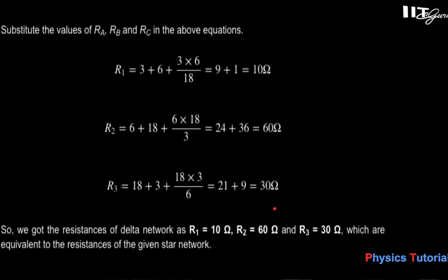Now how to apply this in circuits? In this same video, we'll go for complex circuits, those circuits which we can't easily handle with the help of series and parallel. If you have to solve this without using star delta, then you have to go to Kirchhoff's second law, the loop law, and that will be very tedious and cumbersome work. To avoid this tedious work, we will use a star delta conversion. With the help of star delta conversion, we will immediately convert the circuits into series and parallel order, and safely conclude and evaluate the equivalent resistance.